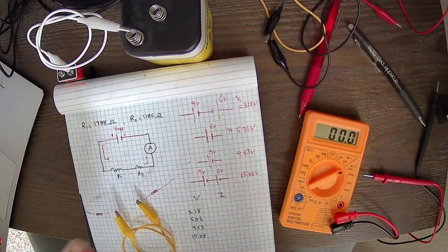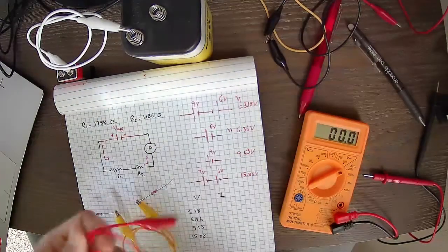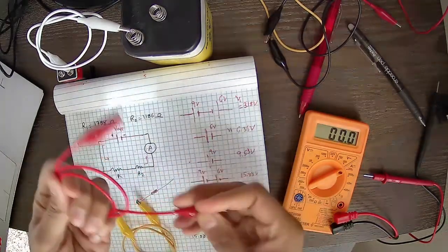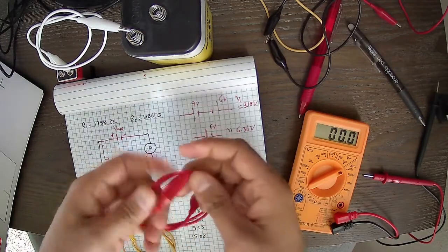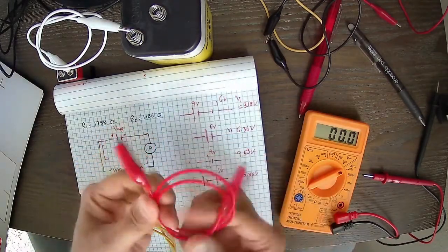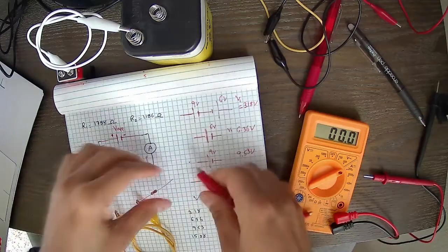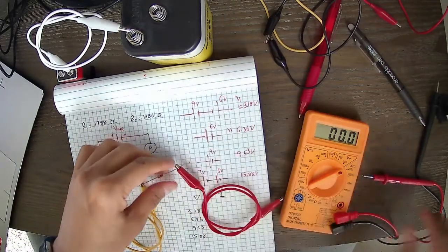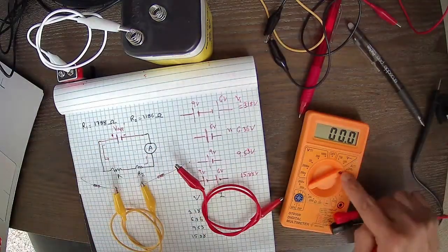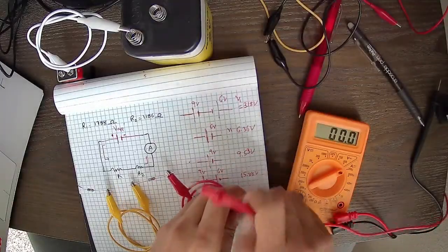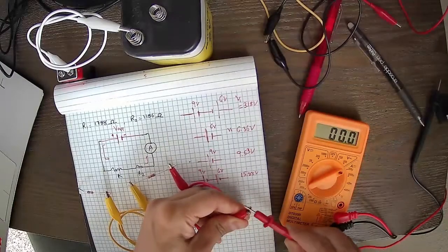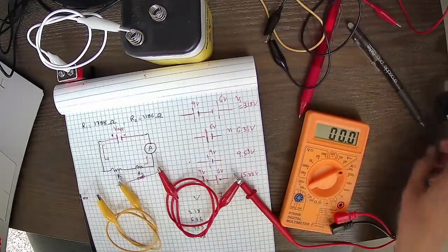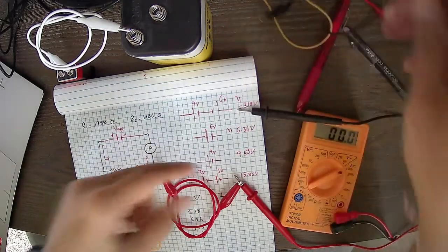I'm gonna just leave it here so I don't have to mess with a multimeter again. I once saw a student doing it in this fashion and it tidied up the circuit quite a bit. Okay, so here, and current is here, so I'm expecting the current to enter through the red input. So I'm gonna hook it up here for the red, and it's gonna leave from the black.